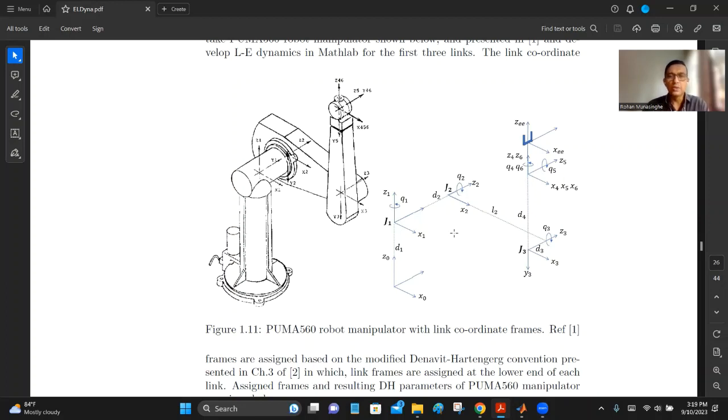Right. So that is why you can see it here. This is, again, not the standard DH frame convention. This is a modified DH convention, all right? Now you can see this is the origin of link 1, and we have the frame 1 there. See that? J1, Z1, X1. So this is the frame at J1. The joint and the frame are at the same point.